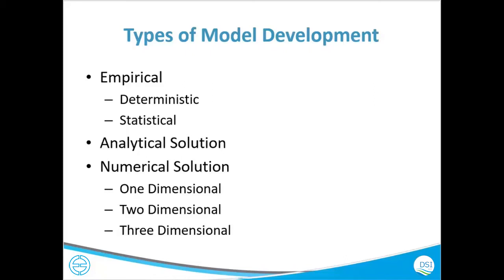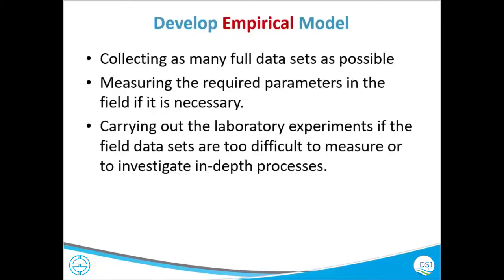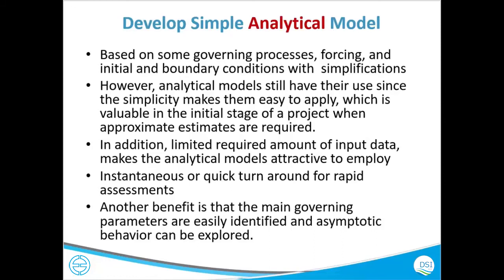But if you have a wide river and you are concerned about the width and the length, then you would want two directions, still with one layer in the vertical, because it's well mixed. But if you are in a complex system and you want to see what's happening at each depth, then you will have to have different depths and different layers in the model. That's three-dimensional.